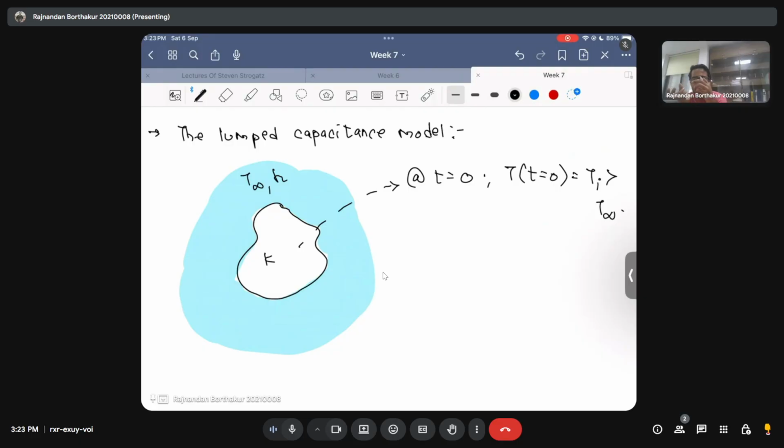So what they do, as I said, is take the temperature of the body to some extremely high temperature, and then in heat treatment processes they quench it into an oil bath or a water bath, or things like that, where the surrounding temperature is much lower. In that case your temperature quickly drops, and this enhances the material property. That's the reason why this process is carried out.